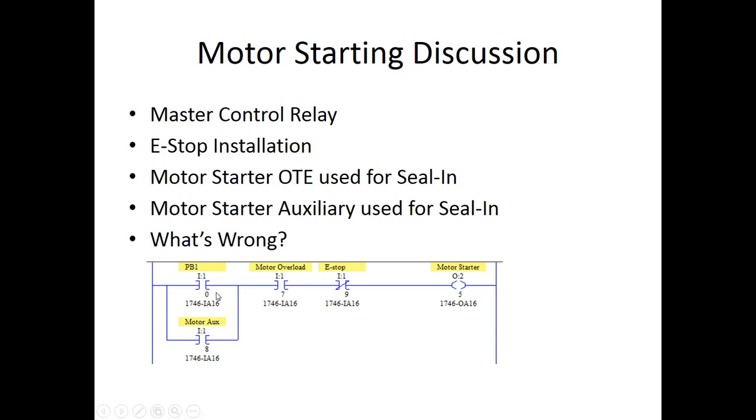It's not. It's not programmed correctly. An E-stop is wired normally closed. So if you take a normally closed E-stop, it will provide voltage to the input module, which will put a 1 into the input table, which will take this XIO and it will open it. It will be false. So this E-stop, wired closed, if it's wired right, is automatically going to kill this circuit. This should be programmed an open contact because the E-stop is wired closed.